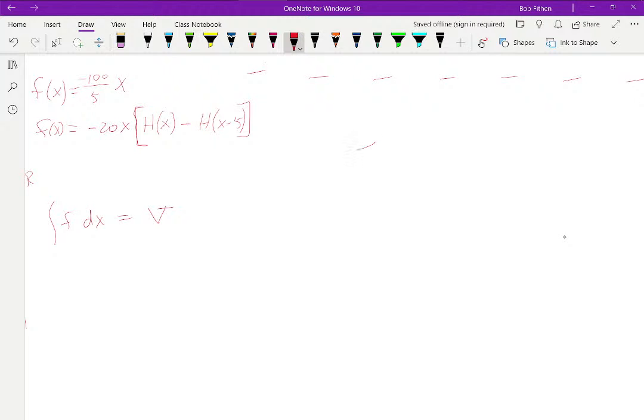So here's what I got. The triangular load sits right here. This is equivalent to a load that's exactly 2/3 from this end, but it's 2/3 of the length of 5.